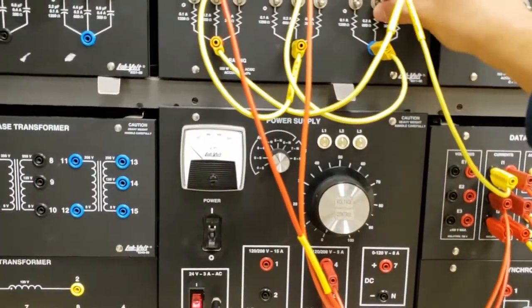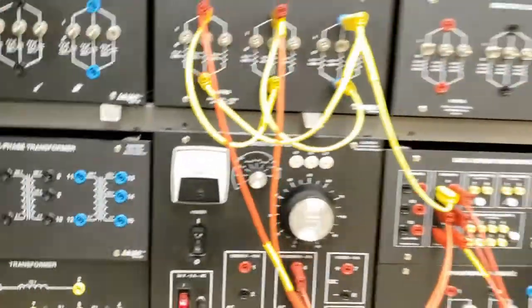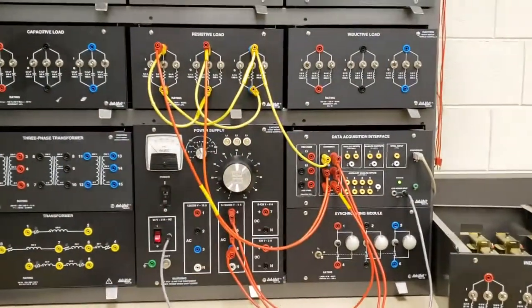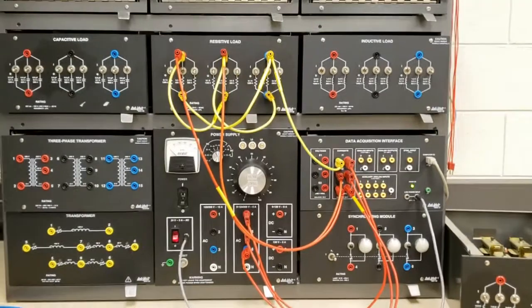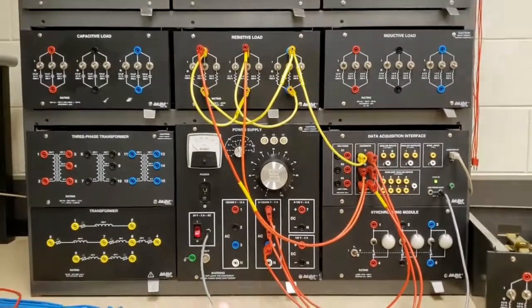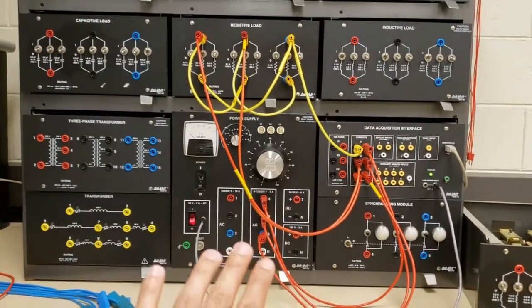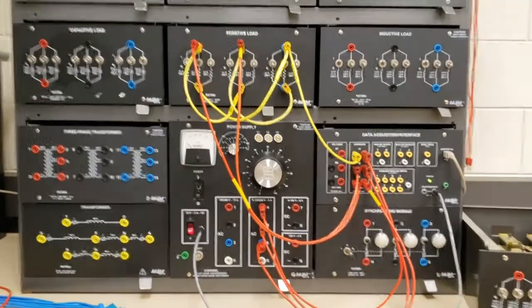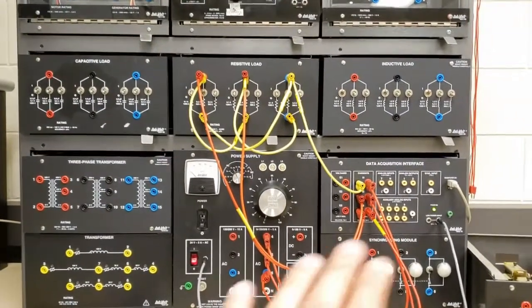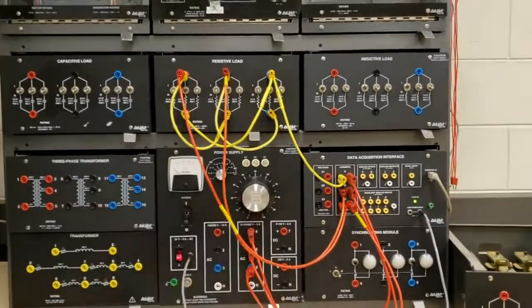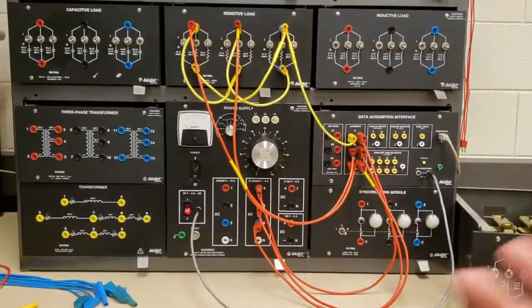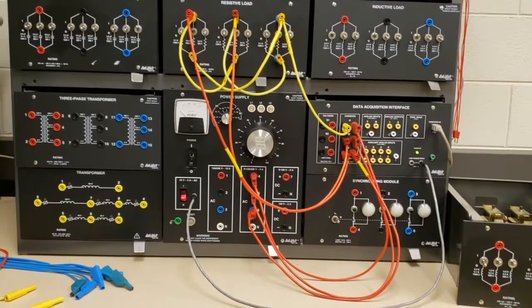But I'm going to go ahead and see what the equivalent impedance is. And remember, the point of this was to switch to a delta configured load while making sure that the currents remain the same. So it's as if the load has not changed from the perspective of the generator. So the generator is still doing its 60 volt thing, supplying the same amount of current, but the load has just switched to a delta load. So the generator can't tell the difference, but you just change it. And that's just a way of practicing how you can change a load between Y and delta without affecting the rest of the power system.